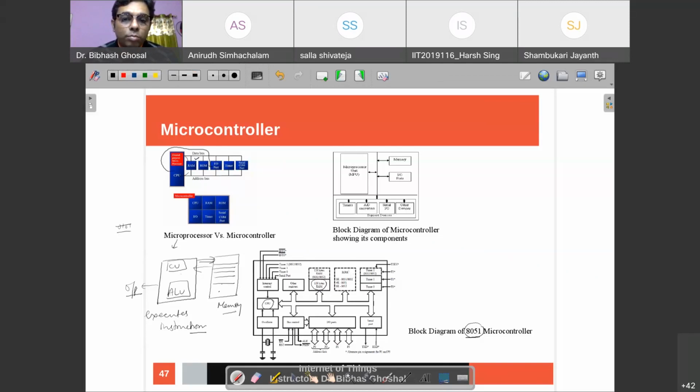It has a ROM, read-only memory, where you cannot write anything. You can only read the instructions from there. Usually this is used to keep instructions and this is for keeping the data. That is how they make this. This is also of 8K size. You have some timers and you have some other peripherals and the buses which are internally connected. So overall, this is one single chip.